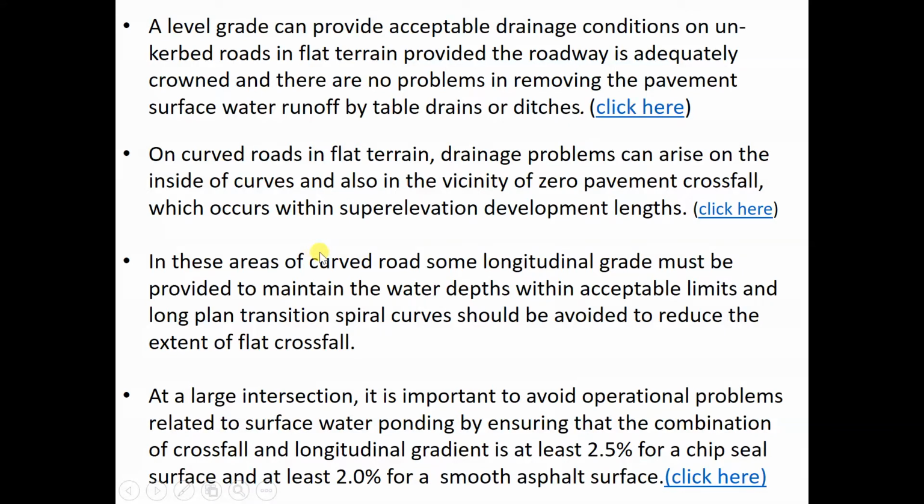So they have one stage of the slope, and then a berm, and along the berm they have drains to collect the water, and then you have another slope. They break it into different slopes, not just a single slope down a high embankment or high cut area. Same thing for a tall embankment: they break it into different slopes with a berm in between.